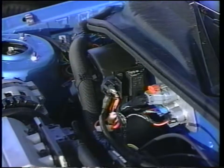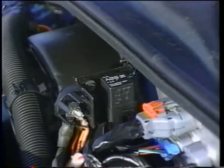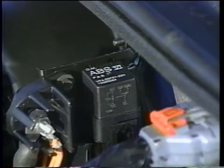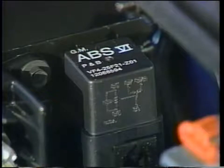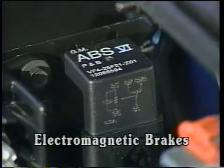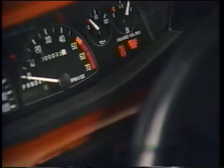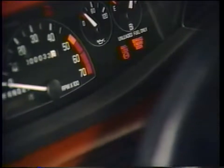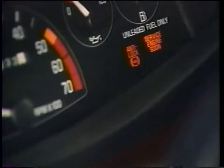Power to the ABS system is provided through the ABS Enable relay when the ignition is turned on. The relay is located under the hood in the relay cluster. The Enable relay switches power to the DC motors, isolation solenoids, and electromagnetic brakes. 2 warning lights are used on the instrument panel. The amber ABS light signals the driver when the ABS self-diagnostics has detected a fault which might cause the controller to disable the ABS system.